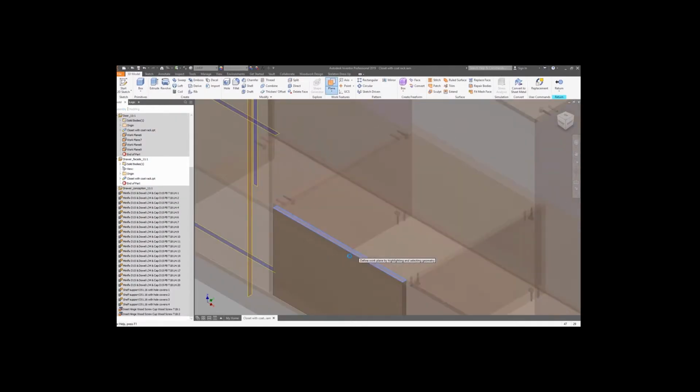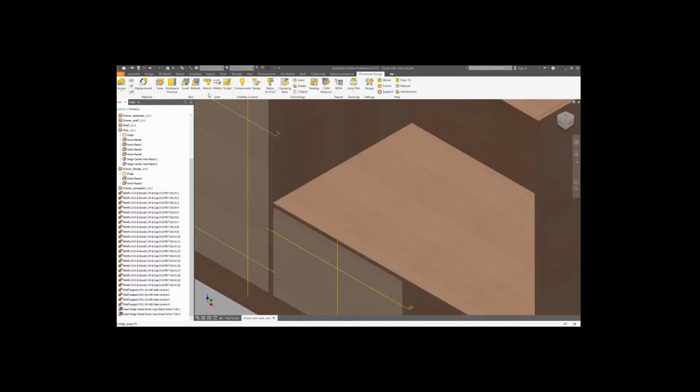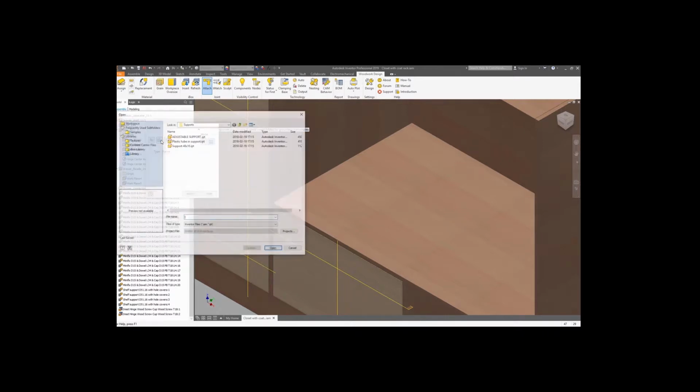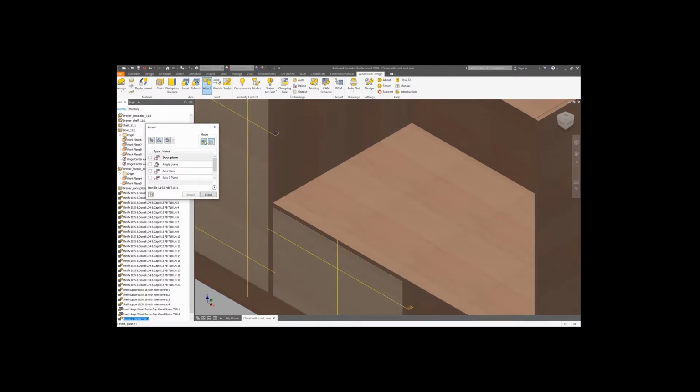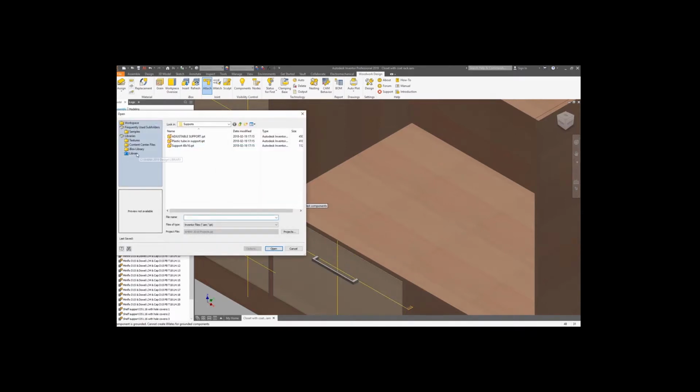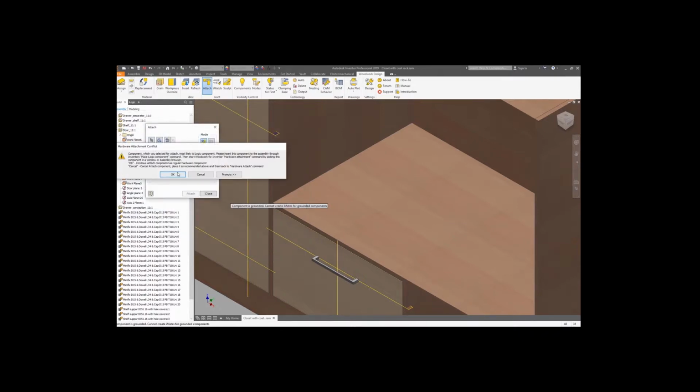Now let's deal with the facade of the door. Again, the position of the handle can be defined by 2 work planes. One is in the middle, the second one defines the horizontal offset. Once it's done, we can use the attach command again to browse through the library structure in order to find handles. Choose the appropriate length you prefer, and then you need to choose the mode. In this case we will pick a single mode, since we want to get one handle at a time, and then again pick the reference geometry, the front, the vertical and horizontal work planes, and the rotation axis.